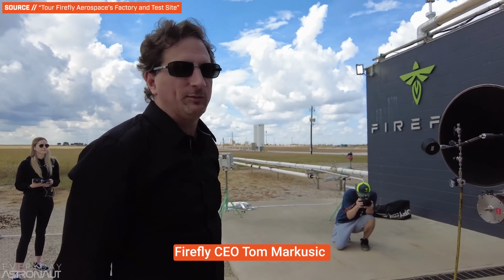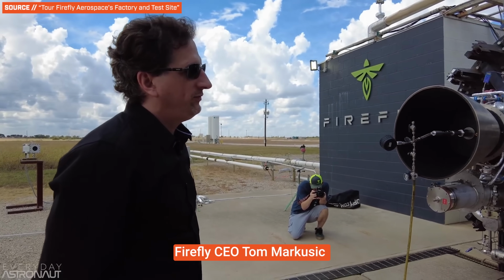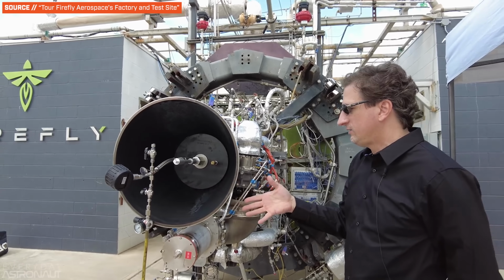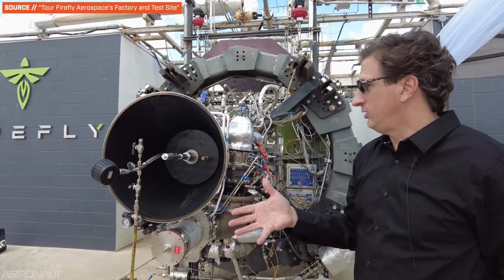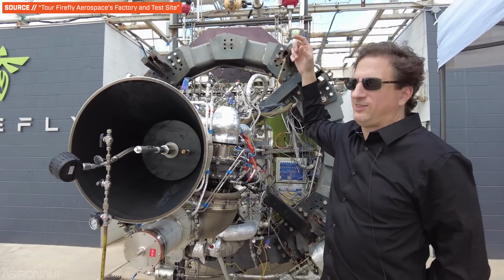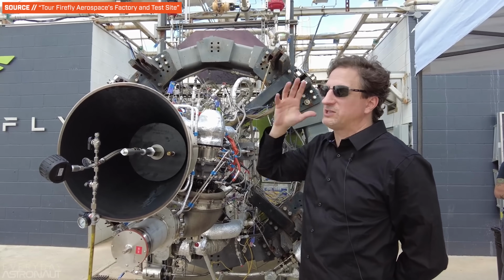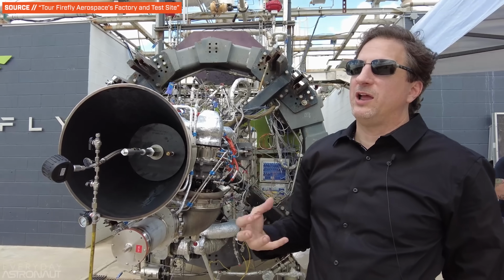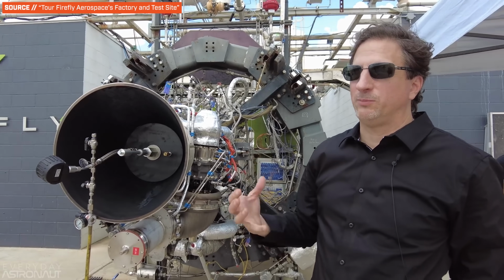In Firefly Space Systems, we were developing a carbon fiber pressure-fed rocket. So on a pressure-fed rocket, to get that chamber pressure, you have to pay for it in the pressure of the tanks. Which means thicker tanks. Thicker tanks. So in the pressure-fed rocket, you're really trying to lower the pressure in the propellant tanks.